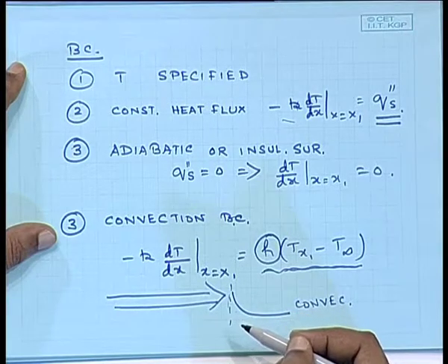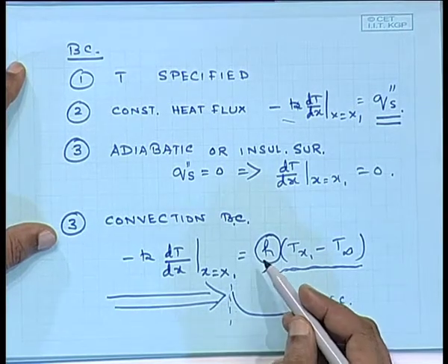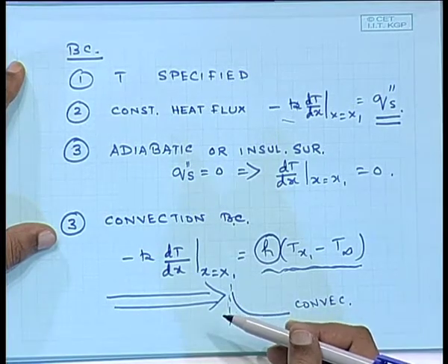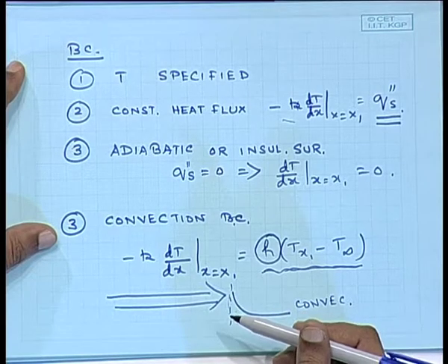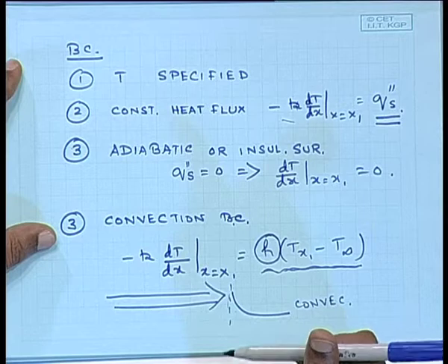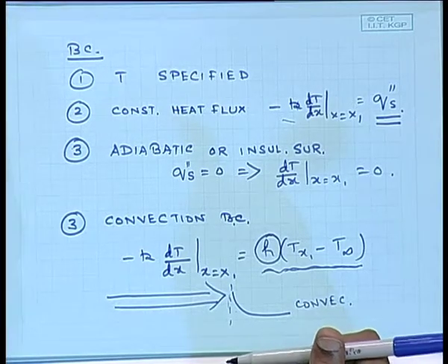That's one way of increasing the H, but whenever you increase H by turbulence, you require certain excess energy to be spent for making that process more turbulent. So, there has to be a balance, an engineering balance at some point. You have to consider what the cost involved for the imposition of turbulence is and the gain that you have by increasing the value of H.